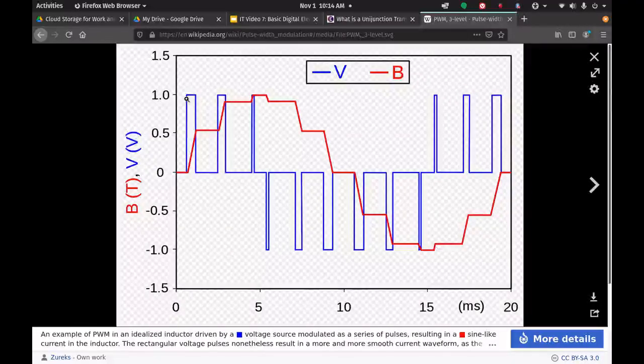So in blue, we have a pulse width of maybe half a second. And so that's going to take our output voltage from 0 to 0.5 for maybe about a second. And then we're going to do another pulse for another half second, and that's going to raise it up to nearly 1. And then it's going to stay constant, and then we're going to pulse it again, and we're going to get up to 1 volt, and then we start putting in negative voltages, and that's going to drop the output voltage.